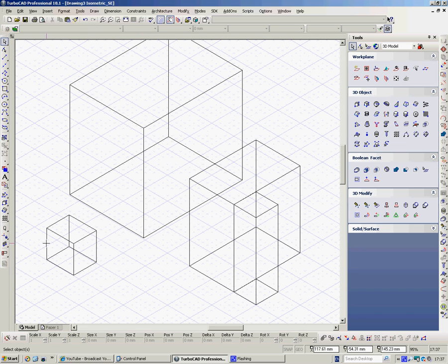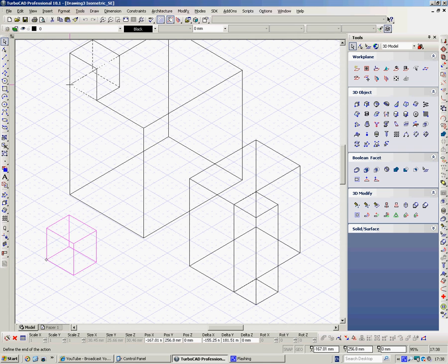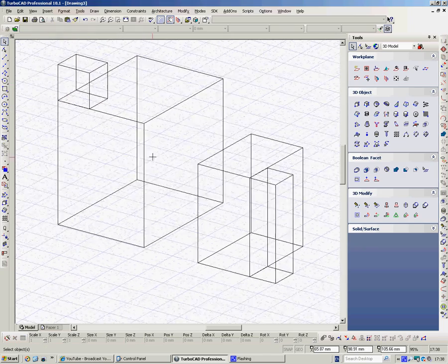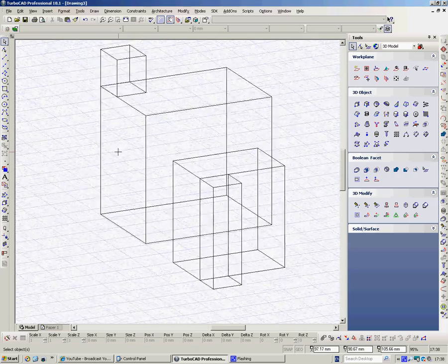But what we can do is manipulate this. We can use the snaps again to position it. So I can select a box. I can hit D on the keyboard to pick up the origin. I can snap the origin to that point there with a V. I then hover over it, I left click, take my finger off, and now I'm carrying it around, and I take it up there, and I go V snap. Now when we skew it, we can see it is there.